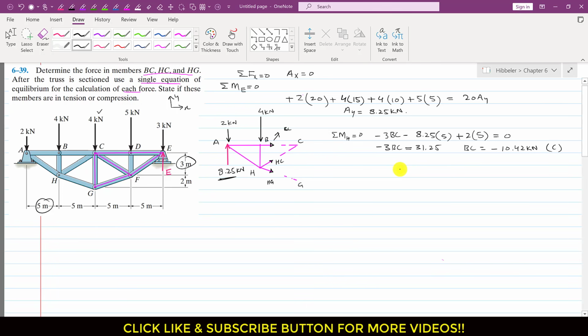Now to find Hg force, what we need to do is apply the summation of moment about point C. We have to select such a point where two forces of these three unknown forces must pass, right? So if you want to find this Hg, then we can observe that this BC force and this Hc force are passing through this point C.